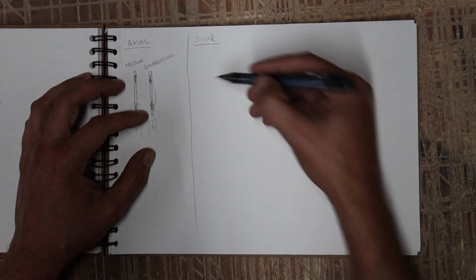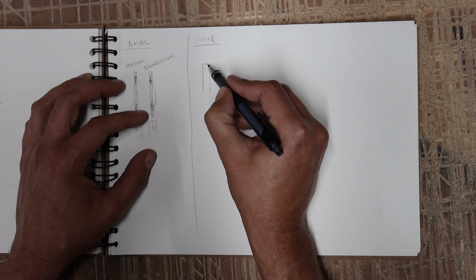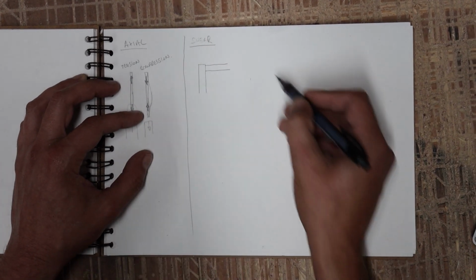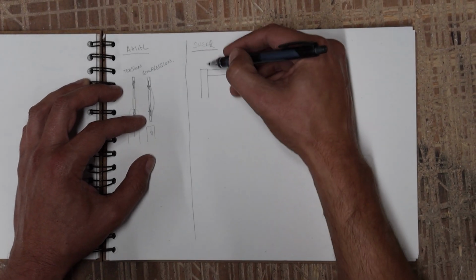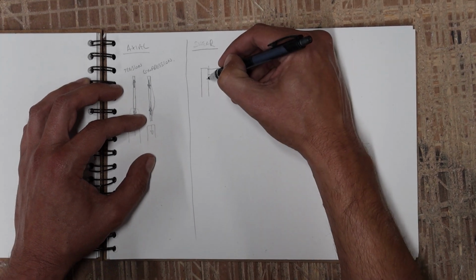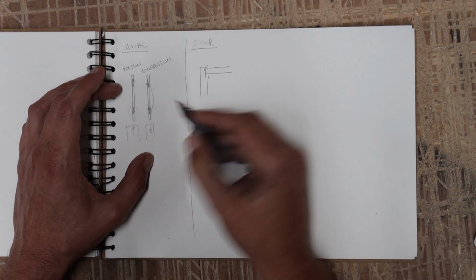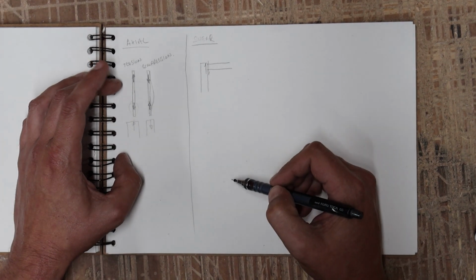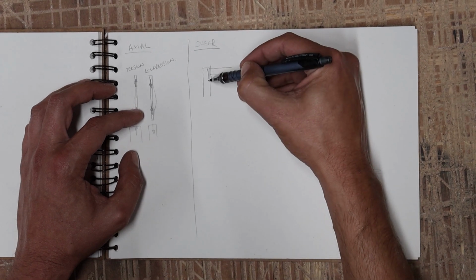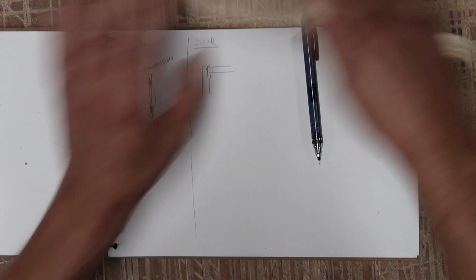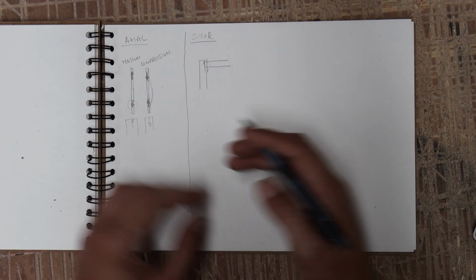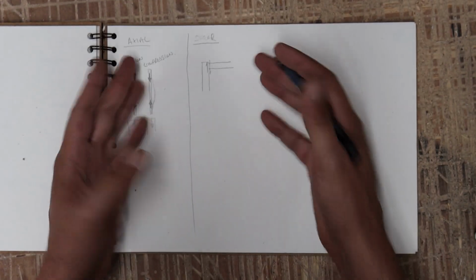If we imagine we've got a column and connected to that column is a beam, then all of the force that that beam is supporting is being transferred into that column by a downwards load here. And the column is required to counteract that the exact same way that this is working. Every force has an equal and opposite reaction. So the shear on the beam comes downwards, and the shear from the column, the opposite reaction, goes upwards. That's what I'm trying to do here. I'm pulling down with one, pushing up with the other. That's a shear load. That's just how it represents itself.